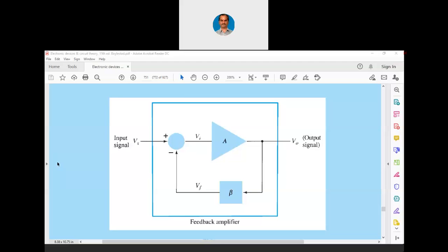Please recall whatever I had discussed when I discussed two curves, two frequency responses, one with the larger gain and one with the lesser gain, and I had shown you how the gain bandwidth product is going to be constant for a given amplifier. So if the gain is reduced, naturally the bandwidth will be increased, because the points at which we mark those 3 dB cutoff are going to be expanded and we will have a larger bandwidth. That is one obvious advantage.